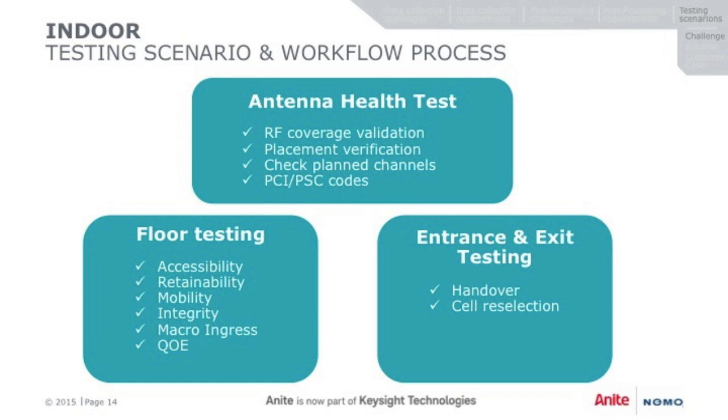Entrance and exit testing, the other block that you see, is mainly when you walk in and outside a venue. This is to analyze the relationship between your macro and your DAS. A couple of things you can do are handover testing, which is in your connected mode, where you can test your handovers, and then you have your cell reselection, which you can test in your idle mode as well.